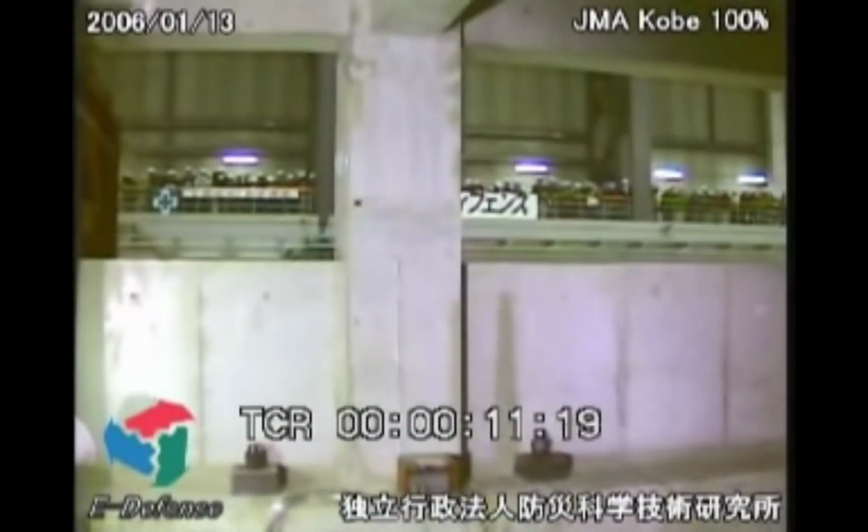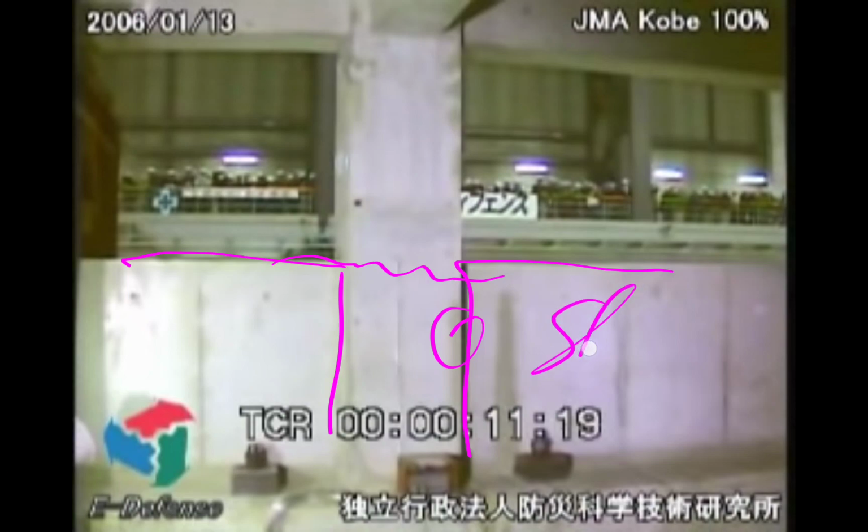I'm going to cut to the chase and tell you that when you see these abutments like this, even with a gap, when the building rattles, this acts as a shear wall, these two sides. So the building shifts this way and that way. This section here can't do the movement with it. It can't shift with it. It doesn't have the flexibility.